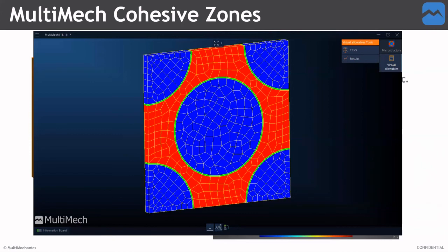And I guess the last question we'll go over really quickly is what type of optimization is performed for the tube. We talked about the optimizer looking for the optimal solution. So do you want to answer that quickly, Flavio? Sure. Our optimizer has a couple of different algorithms, including design of experiments and a few other nonlinear ones. The one used for the tubes is genetic algorithm, which basically creates a population of different designs for the layup. And then we iterate and then create different populations based on the ones that perform better, and then try to search for the best and optimal solution.